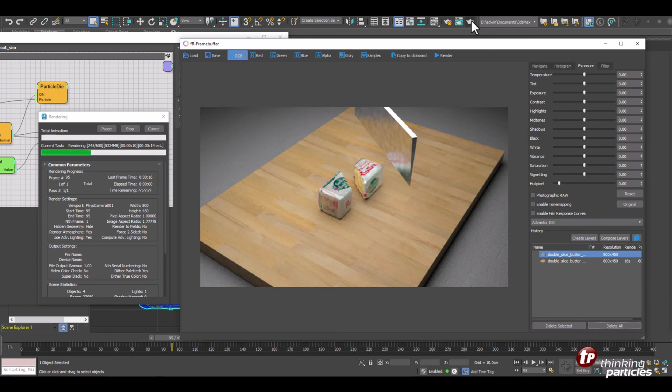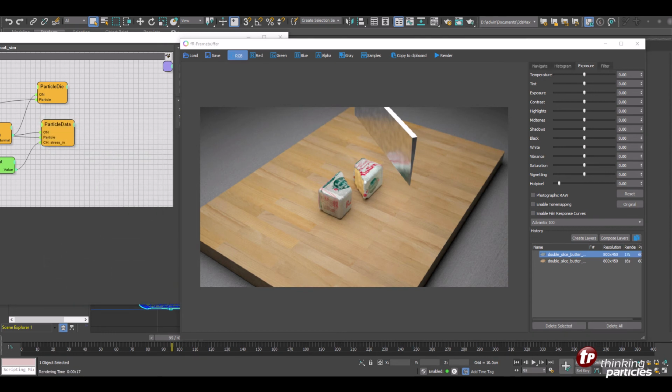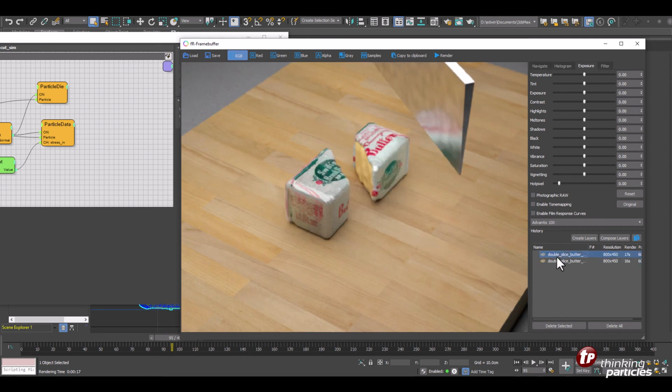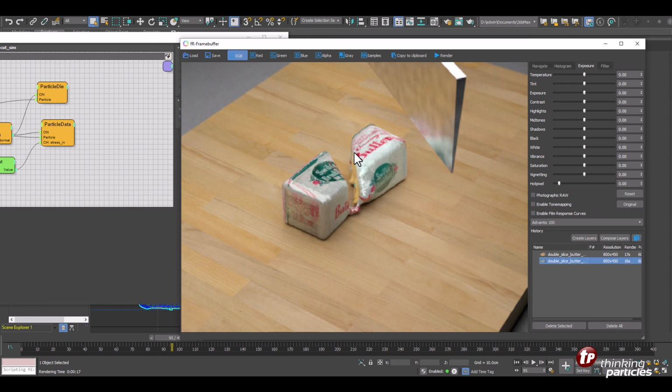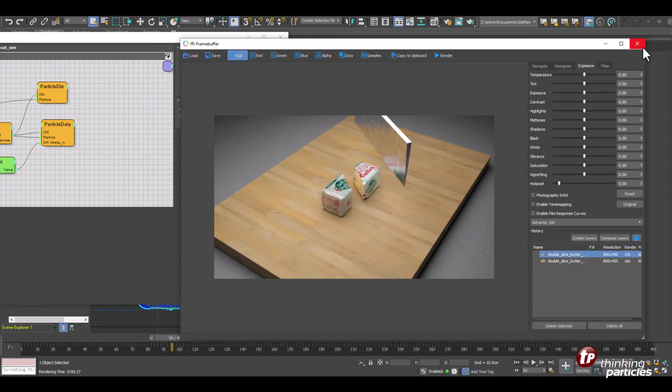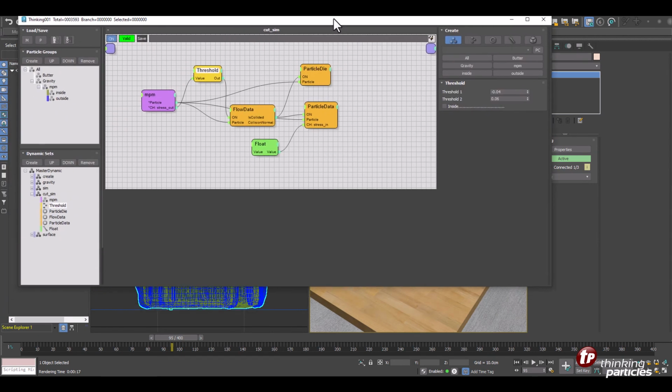Keep in mind, this is a tutorial video, so you can up the resolution so that it gets crisp and nice and fine. But for the sake of the tutorial, we have this lower resolution, but you can clearly see the dynamic set that cleans up our continuum mechanics effect is working. So we have full procedural control over our continuum mechanics solver. And that's really a powerful feature that you won't find in any other product right now on 3D Studio Max. So we can control our material point method in detail in a procedural way.